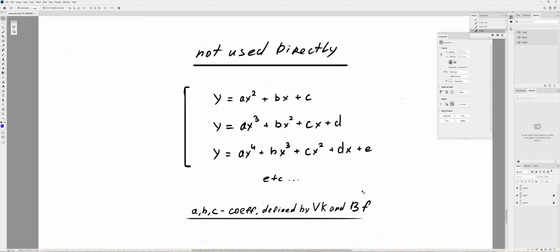If you have 100 control vertices, you have a really big amount of derivatives. In real life, in real practical examples, Alias works with a specific tolerance. Alias rounds the values as well as any other computer. So the fluctuations of the complex polynomial, the more and more complex it becomes, are very difficult to control.